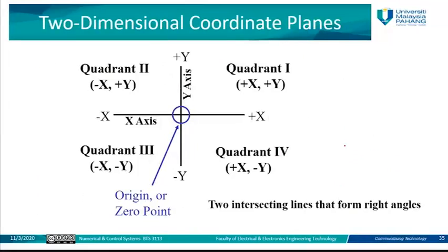So usually for the CNC machine, we need to define the origin point. I already also mentioned this in chapter 1. I said this is the point of origin or 0, 0. Usually we need to define some reference point in order to move from this reference point. If I say move from the origin 2 to the right, that means I am going to this 2. If I say move from the origin 2 to the left, it will go to this -2. If I say go 1 up, it will go to 1 here. 1 down, it will go to -1 and so on.